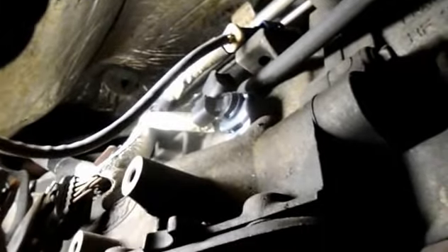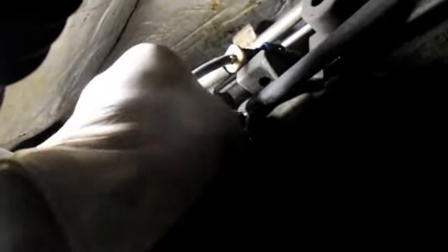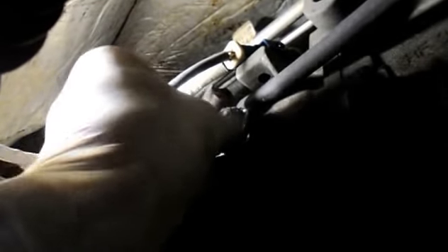All right, we're going to put the replacement back in. Push it all the way in. Catch that bolt that we previously took out. Screw it in by hand as far as you can. And then once you've got it screwed down by hand as far as you can, you'll get on there with the ratchet and just snug it in. You don't have to go real tight because you're going into aluminum. So you just turn it until it's snug.